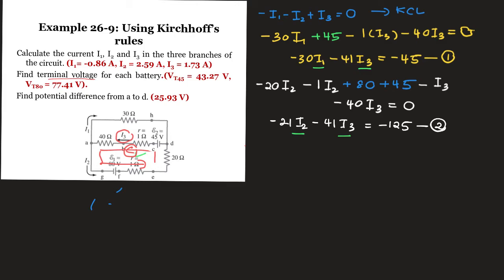So I'm going to change this one, which means I'm going to make this equation with the unknowns of I1 and I3. Please make sure that you don't change the same unknown. If you change it, it's going to be a lot of work; you are going to repeat the same thing. You change the unknown that is not the same in both equations, like I1 or I2, so you can choose I1 or I2.